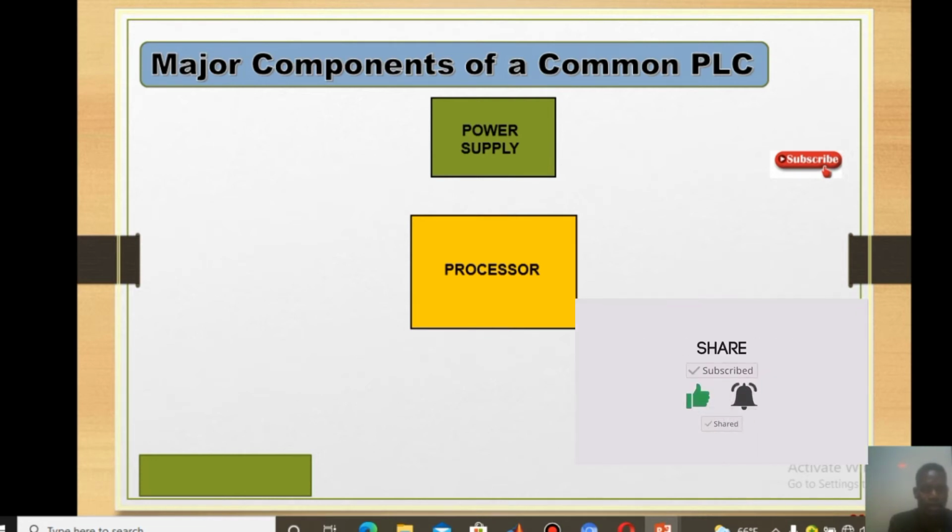So we have to go back and review our lessons, especially when we think about the power supply. Power is not randomly supplied for these PLC systems. When we supply random voltage, whether AC single phase or three phase, directly to this processor, we completely burn and damage our system. So we must take care when we supply power to PLCs physically.